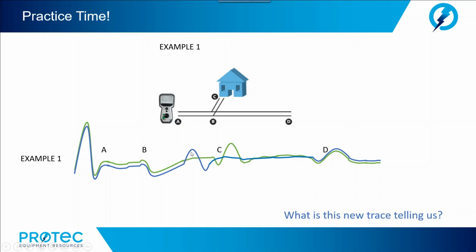Instead, we see a large impedance increase very close to the tap position or the branch connection point. This would imply that we have possibly an increased impedance or open circuit. Since we're not seeing to the house any longer, we can conclude that we have an open circuit in the branch feeding into the client or to the house.